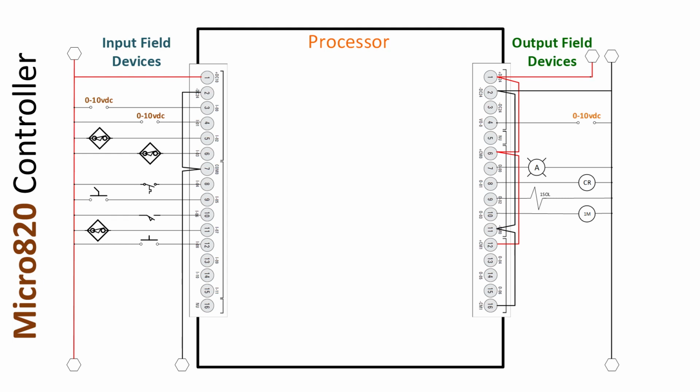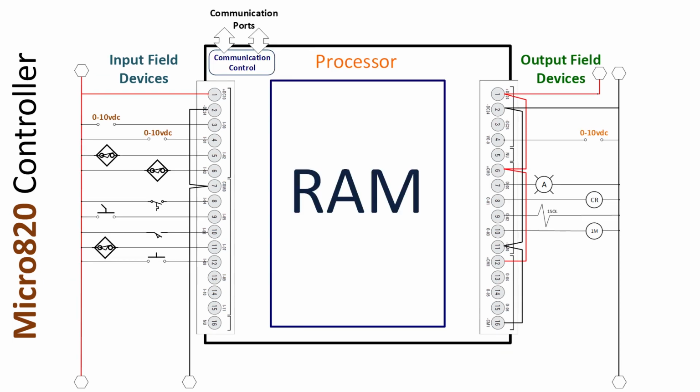Let's bring our RAM back into view. So here's our random access memory. Very important, also we added communication ports. Now we switch to the Micro 820, which has two ports. It has RS-232/485 and it has Ethernet IP. So one port will support 232 or 485. All the contact that you're going to make is to RAM via one of these COM ports. Downloading to RAM, online monitoring in RAM, and editing and uploading, not to mention flashing firmware if that becomes necessary.